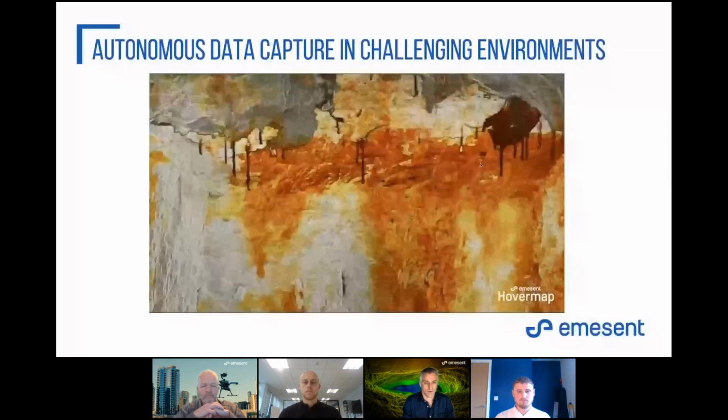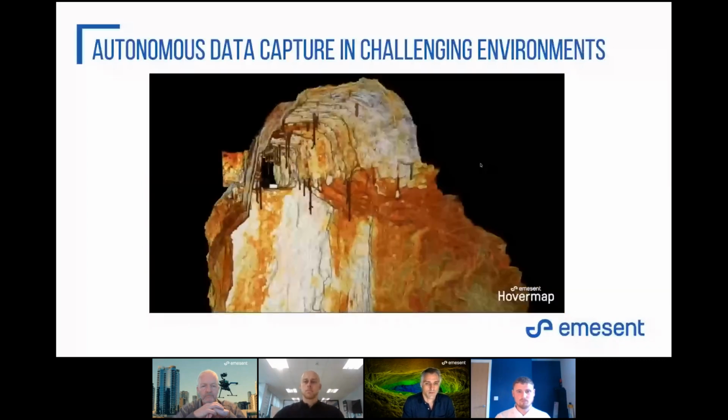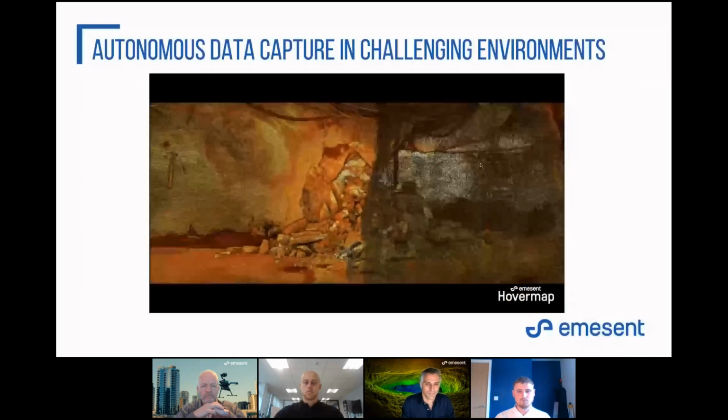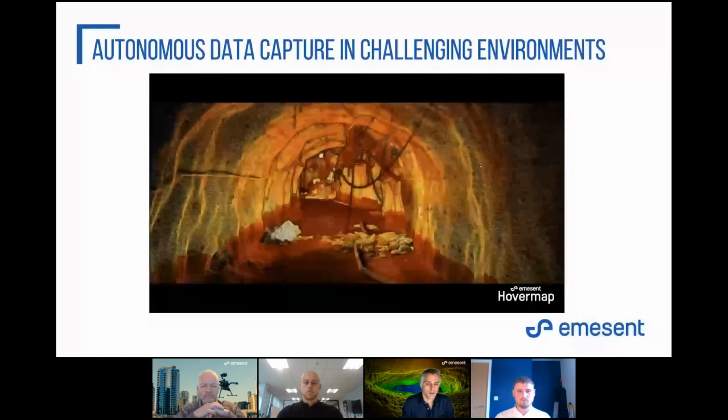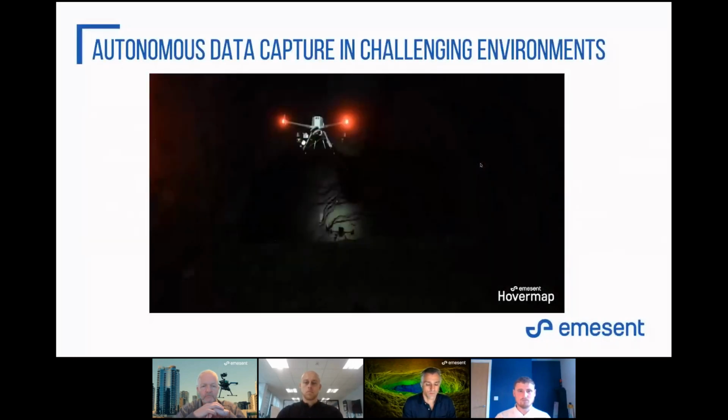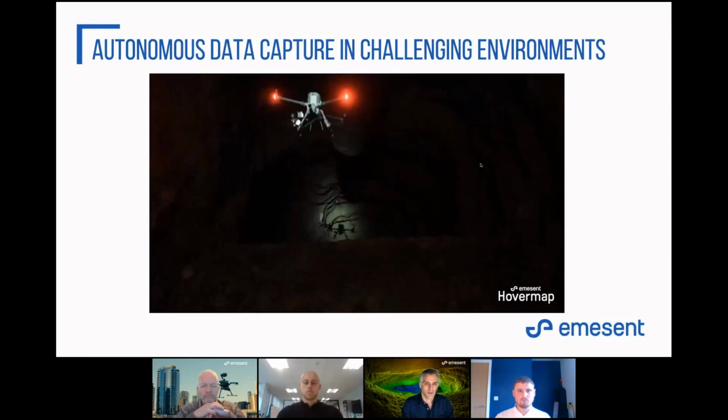And it's used every day in these kinds of environments to capture data that just was not possible before, for doing volume estimates, convergence monitoring, looking for rock bolts to make sure that the roof support is adequate. And as you can see in this example, going into areas that have had significant rock falls and are a safety hazard. So I won't go into too many details with the mining workflow and examples today. We'll focus on some other use cases, but I just wanted to show what the system is capable of in those challenging environments.